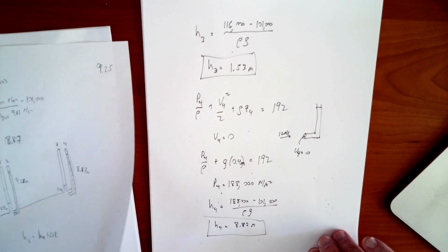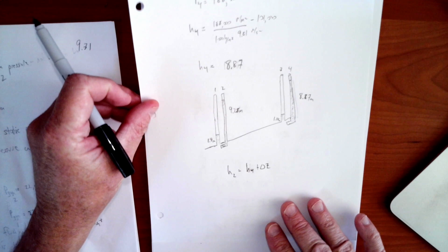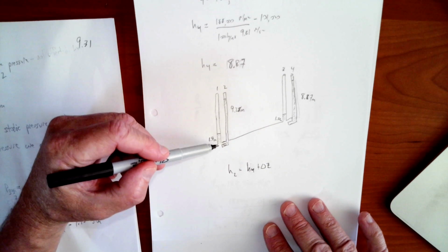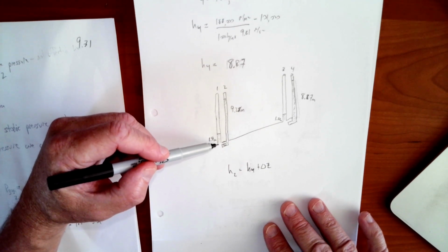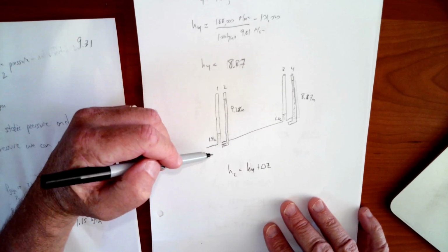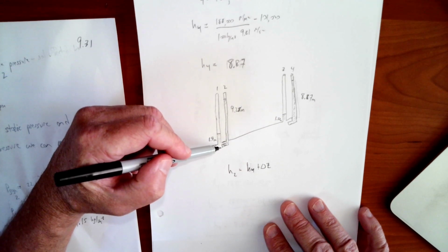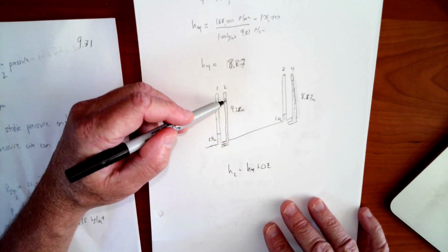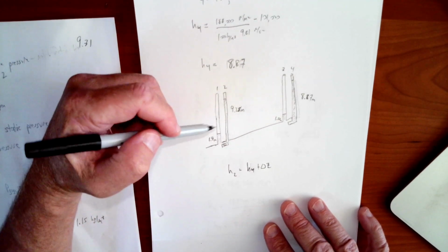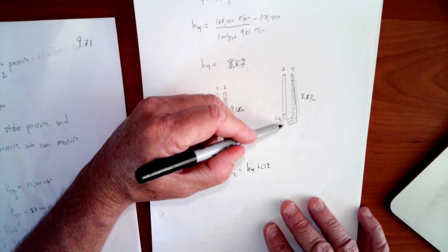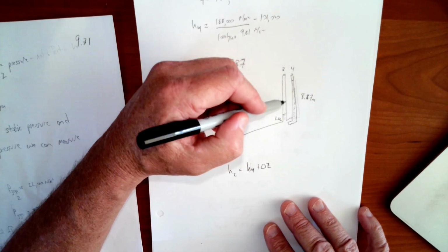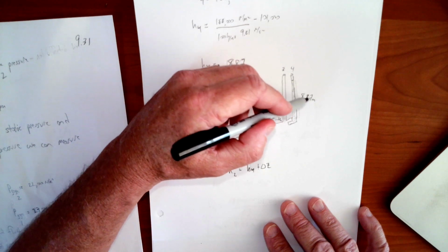So finally, I'm just going to show you a little picture of the final heights here. So we had 1.9 height for the opening 1, which had the opening facing downward, and so no velocity loss there, 12 meters per second velocity, low pressure, but higher than atmospheric pressure, so it still has a positive H. Then this one is really large because the velocity drops to 0 at the entrance to pipe 2. We get this big change. This one drops a little bit more because it's higher in elevation than H1 is, so that pressure is less here up at this higher part of the pipe. And this pressure here is also much larger than H3. The H4 pressure is high, so you get 8.87 meters of height.